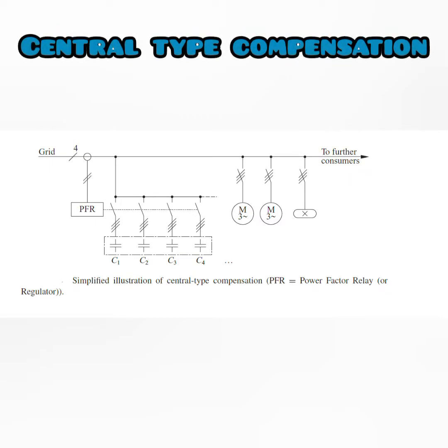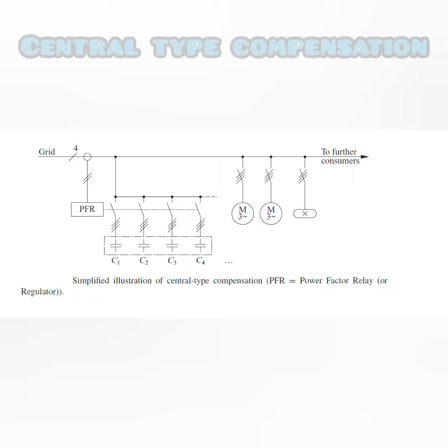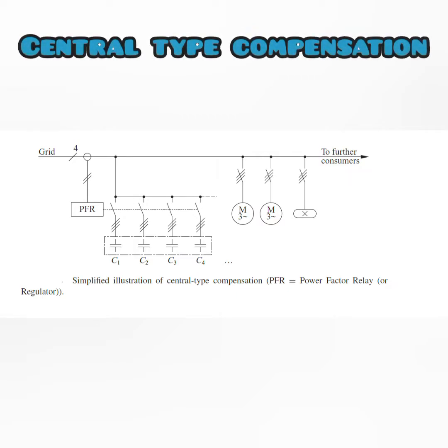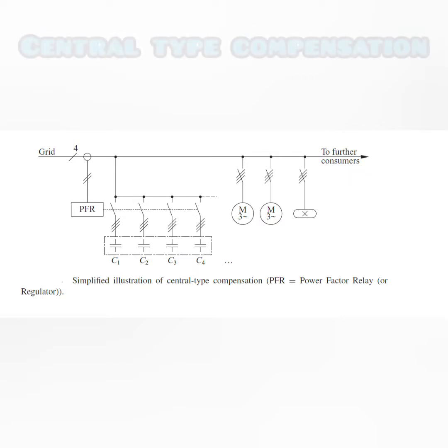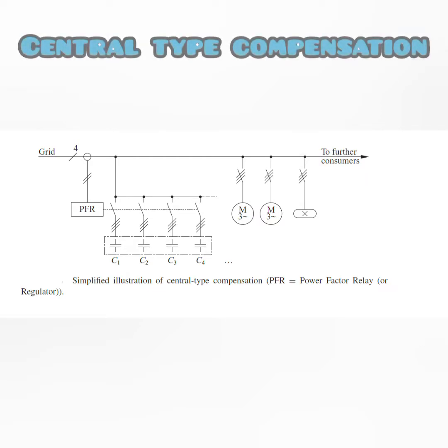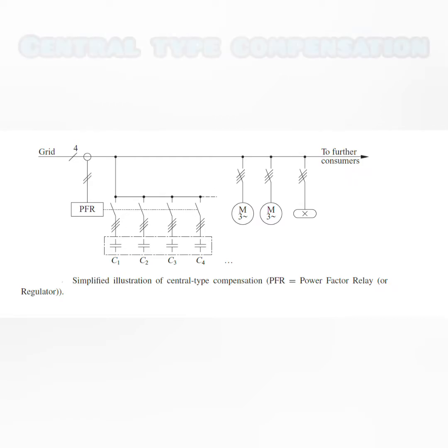Here we are using one power factor relay for the automatic regulation of your compensation, which means your reactive power. So the reactive power will be connected according to the number of motors or machines connected with the load. That's why it is known as the automatic regulation of your reactive power compensation.